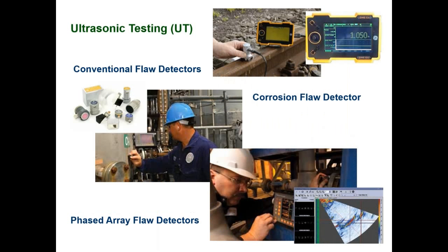There are ultrasonic testing methods that can be used to quantify the extent of corrosion or the effectiveness of a coating material or detection of flaw. This can actually be arrayed. So you can have one site ultrasonic testing, or you can have an arrayed site, which gives you a sampling of a large arrayed area that can allow some type of mapping.